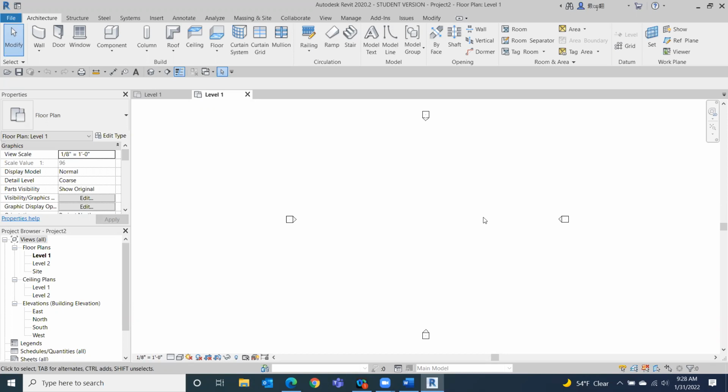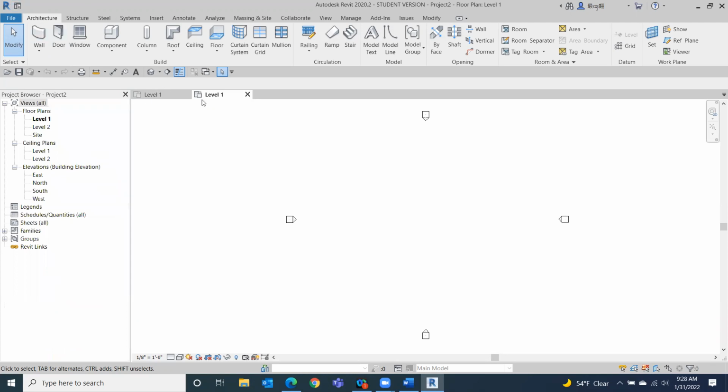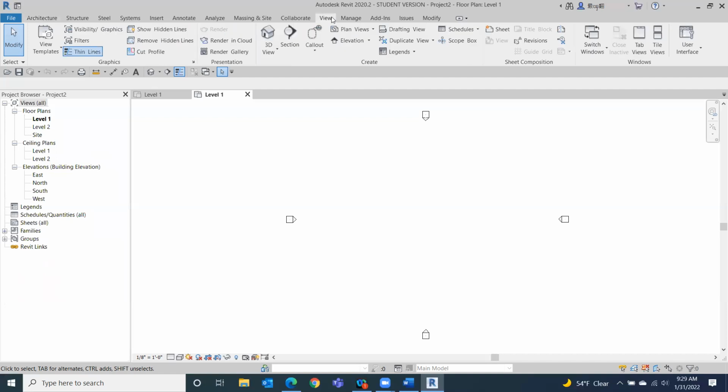So the big drivers that you need to remember ahead of time are tab, panel, and tools, how to navigate through that, and how to use the properties and project browsers. If you do accidentally close one, because they're real easy to close, it's going to happen. If you just do that, it's going to disappear. So you can go to the View tab, all the way to the right to the User Interface tool.